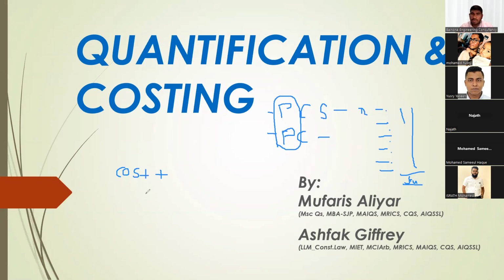What is remeasured? You will see a rate in the bill of quantities, and the quantity will be measured on site in the interim payment. That will be multiplied by the existing rate for the similar item. Then it all adds together and will be paid as a remeasure. Similarly, cost plus means the contractor cost, plus they agree a percentage. That is how the contractor's overhead and profit is agreed during the awarding of the contract. Then they pay the actual cost of the contractor, plus the overhead and profit. So that is cost plus.